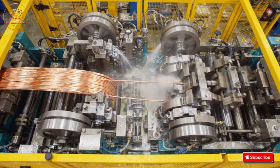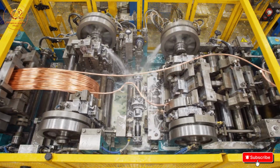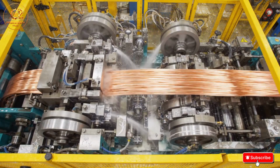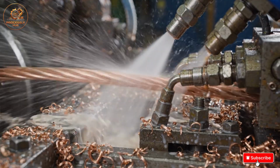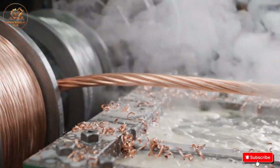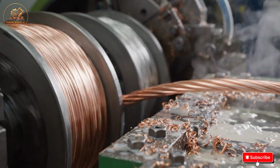The conductor continues through progressively smaller dies. Each reduction increases the wire length dramatically. Continuous cooling prevents overheating during high-speed drawing. Lubrication protects both the wire and the drawing dies.